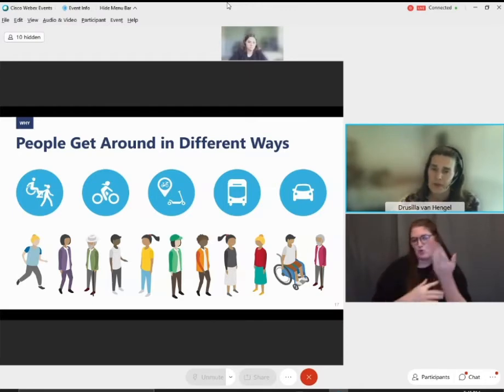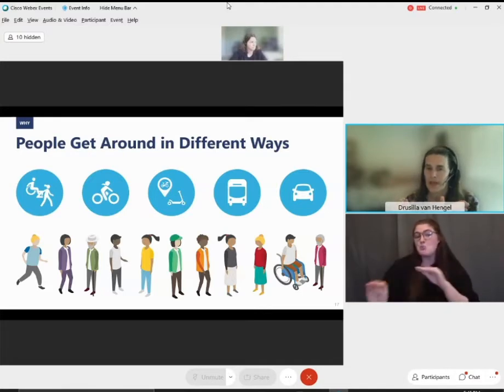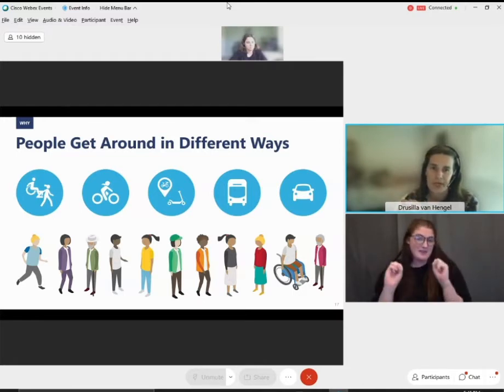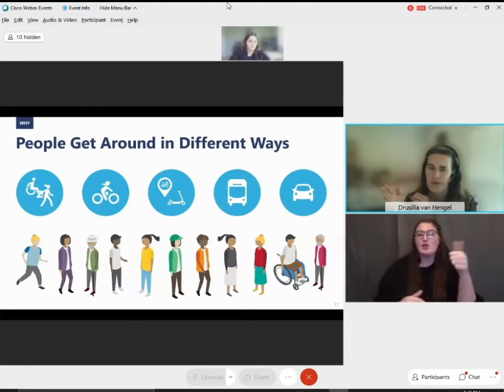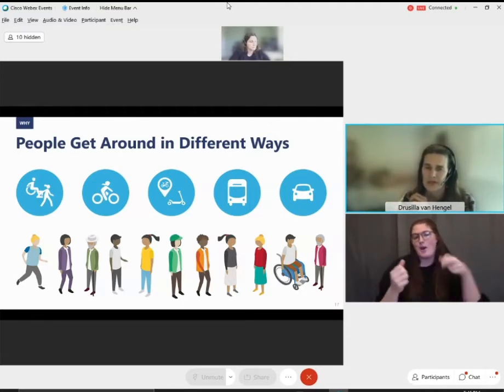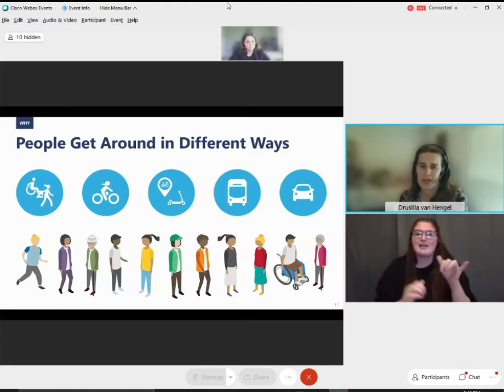Concurrent movements of vehicles who are permitted to turn in the same phase as people crossing the street on foot pose safety risks that can be eliminated by adding additional signal phases or prohibiting movements. At uncontrolled slip lanes, motor vehicles and pedestrians are in conflict with each other as people turn off the corridor and people crossing along the street have movements that happen at the same time.